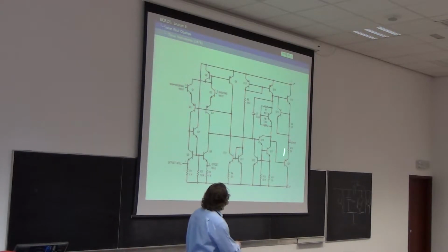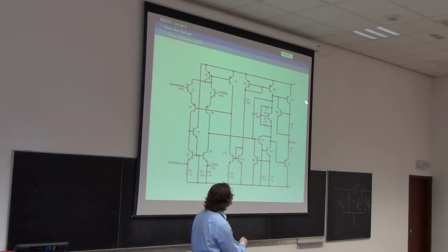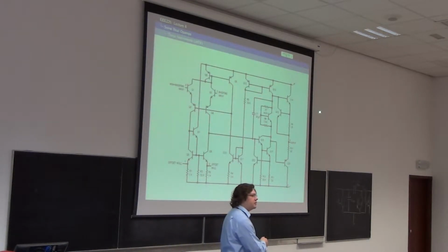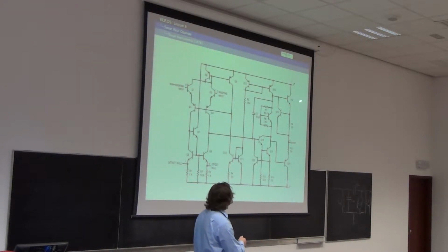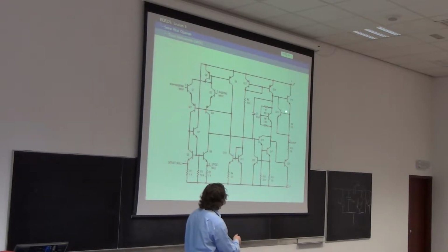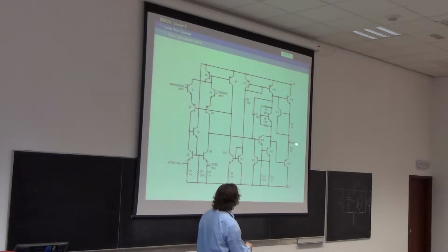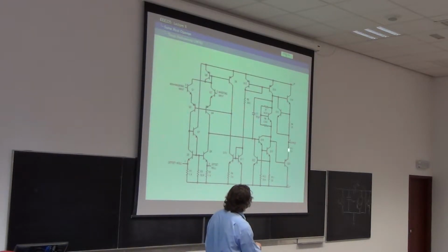If you didn't catch that, let's assume I put a too low resistance on here and I drive a big current into it. Q14 is very unhappy about this, gets quite warm, might blow up, and that's the end of our op-amp. The big current that flows through Q14 into our load, which is too low resistance, must flow through R9, and when it does, it will develop a voltage across it. And that voltage, if it gets to 0.7 volts, will turn on Q15, and Q15 will steal some base current from Q14. Some base current will go down there and end up going into the load, or could end up flowing a quiescent current down there as well. It doesn't really matter where it ends up.